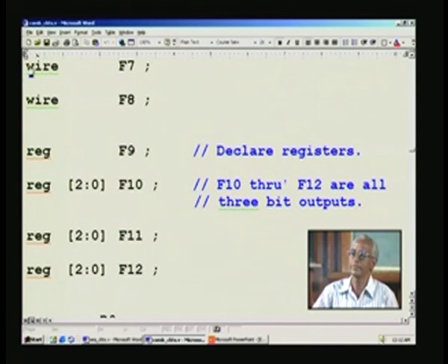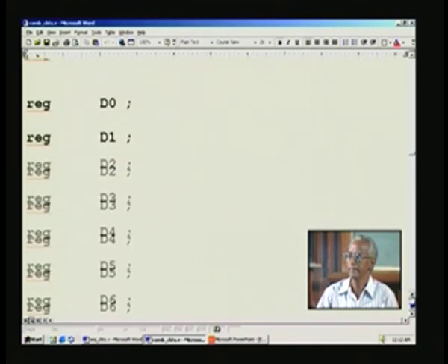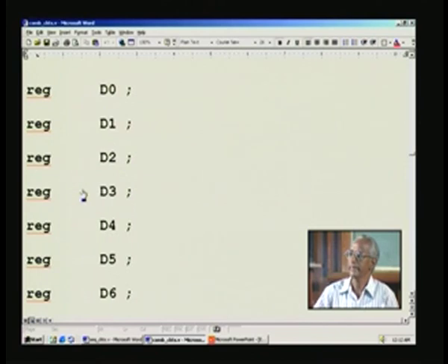So for assign statements you can say wire, and for always block, whatever output, all are with reference to the outputs only, not the inputs as such. And you can refer to it as a reg in always block, whatever signals come in that. Once again you see here for reg multi-bit, it is through this, and for single bit we have this.